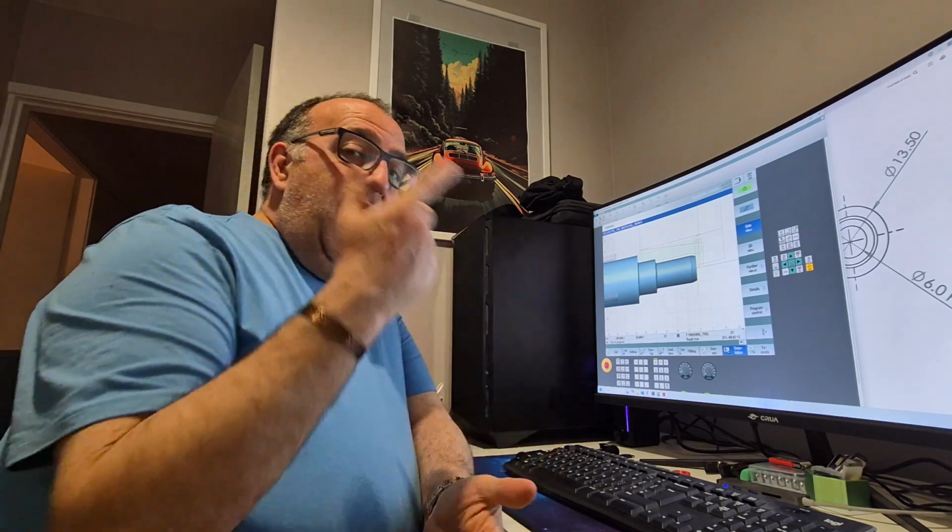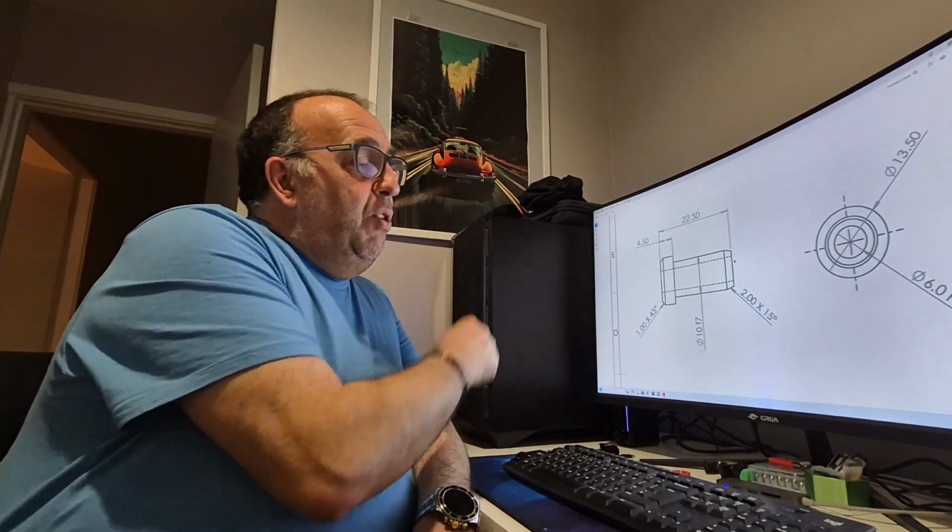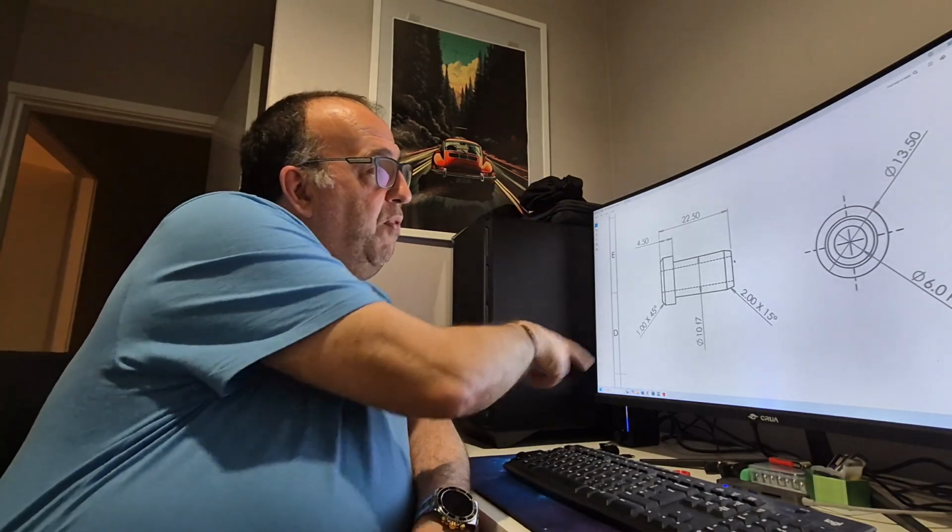Okay, right, that's the end of this video, but for the next video, part 3, it's going to be doing the drilled hole that we've got up there. We need a spot drill, a 5.7 drill, and a 6mm reamer, which I showed you how to load up in video 1. This is the simulation. On a machine, they have to be physically in, and the tool lengths set up as well. Then once we've drilled the hole, we want to part it off and produce this rear chamfer before we finish parting off.